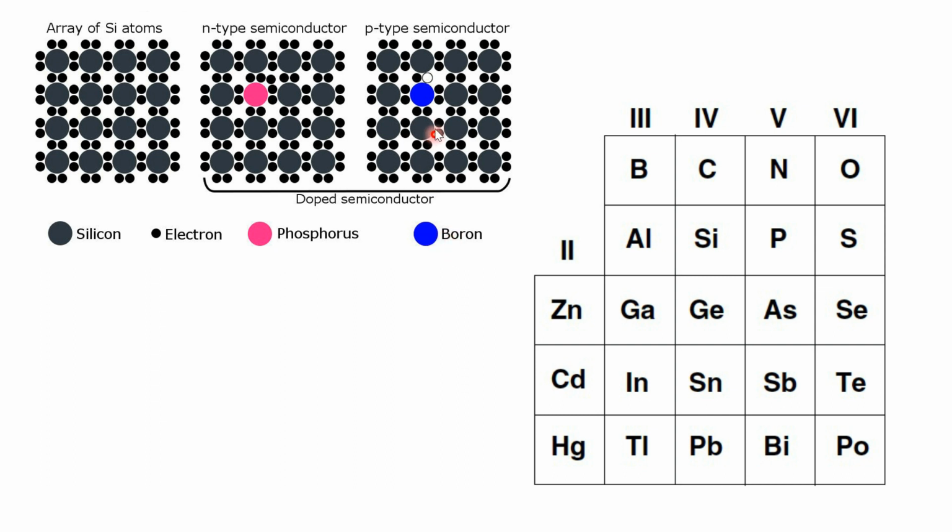So next is the case where it is doped with boron, that is a trivalent material. When the silicon atom is replaced by a boron atom, it has only 3 electrons in the outermost shell. Therefore, instead of an excess electron, what happens here? A hole will be there. Therefore, we can say that the number of holes has increased and the material has become a p-type semiconductor.